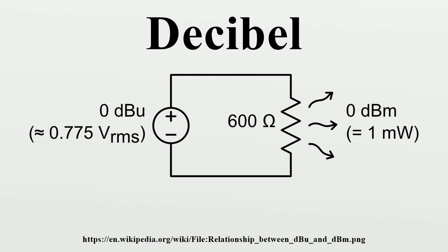If two machines each individually produce a sound pressure level of, say, 90 decibels at a certain point, then when both are operating together we should expect the combined sound pressure level to increase to 93 decibels. But certainly not to 180 decibels.